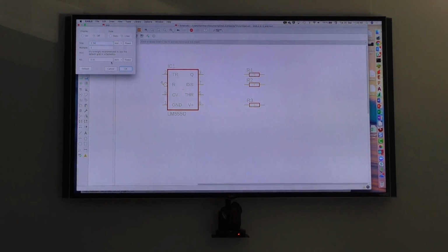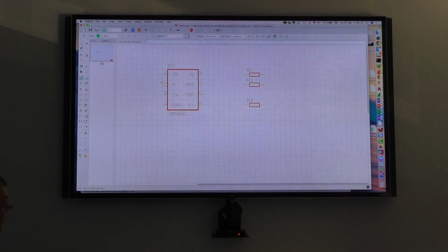But here again, do a proper artwork. Work properly and use this grid. It's very ugly if you zoom in, you see the net jumping this way and then going straight along. So it makes sense to work in this grid. Okay. If I switch to millimeter, I can also display the grid if I want to. So then I see this in the background.